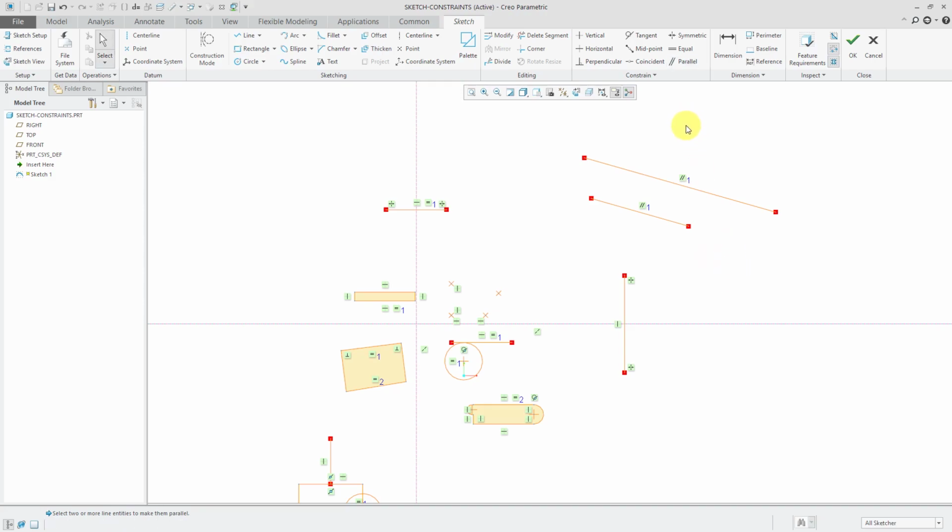I mentioned how you can just hover your mouse over one of these different entities and it'll tell me what the constraint is. From the constraint dropdown, you do have the ability to pick a constraint and then constrain, explain, but it's really kind of unnecessary because, again, just hover your mouse over the name of the constraint. The one advantage is that it will highlight the different entities in red when you do that.